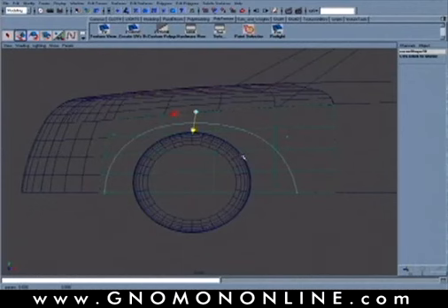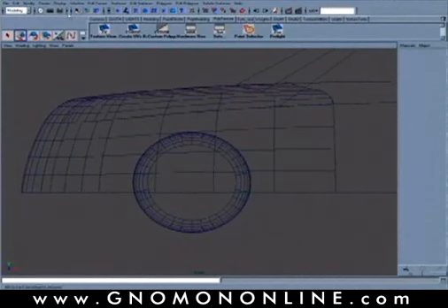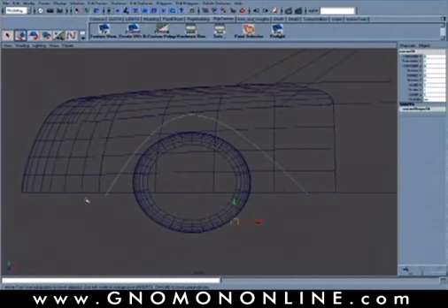This can be my trim curve, or I can opt to just draw this from a side profile without using the live behavior. So I'll de-live that surface and then go in again, but this time I want to make sure I definitely go outside of the surface so that when we trim it, it's not going to be a problem. So I'll snap it down to the bottom here, come up again back towards the top of that surface, and then come back down, exiting the surface at the bottom. So again, we have our arch, but this is not a curve on surface this time.